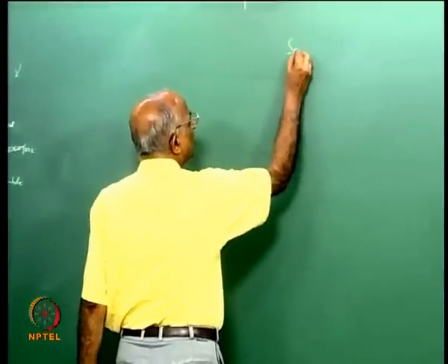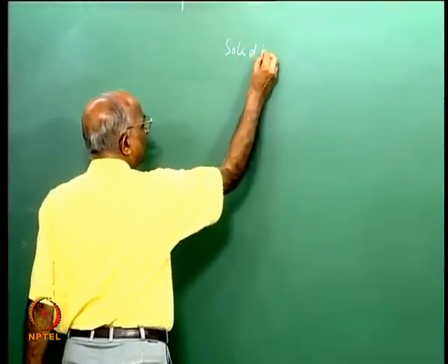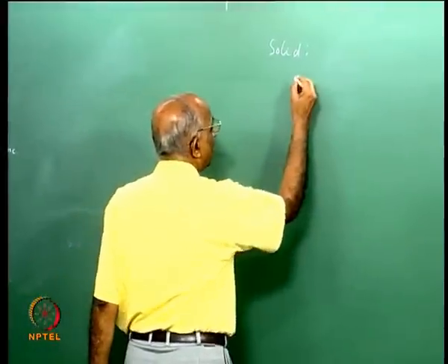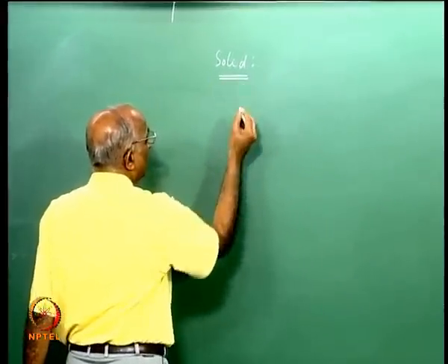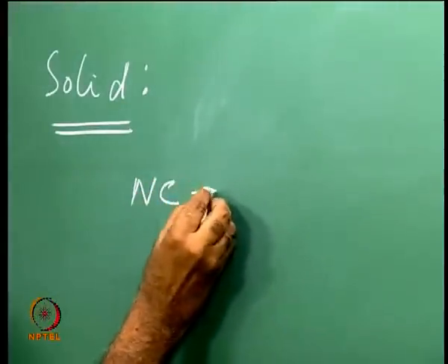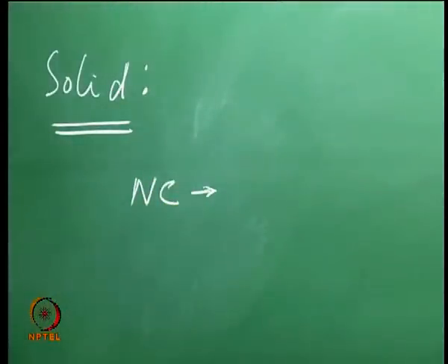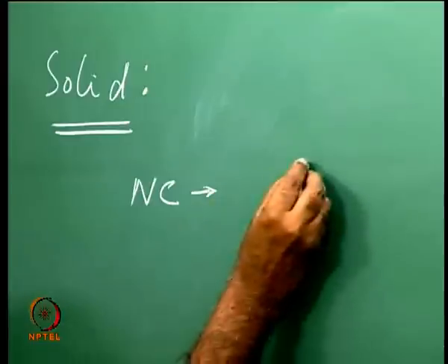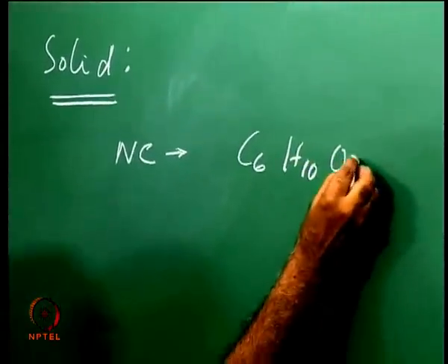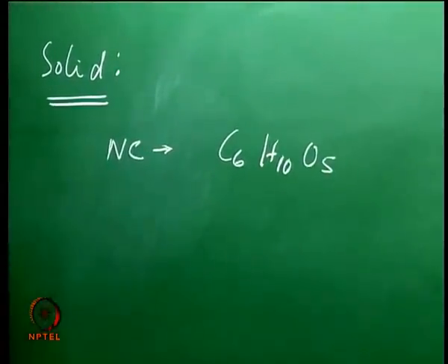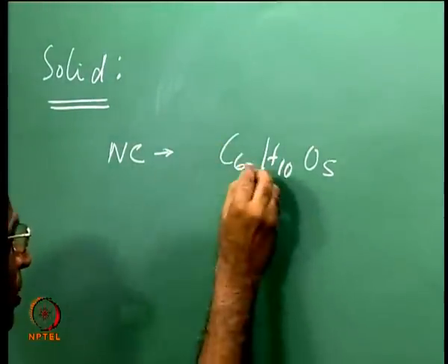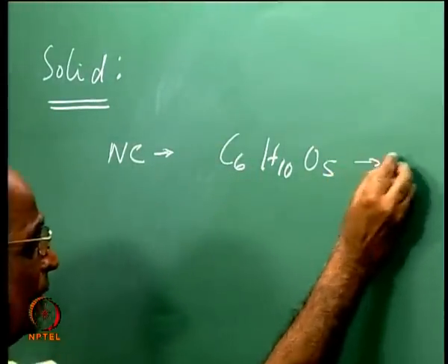Well, solid propellants, we have already seen the different chemicals. Let us start with the chemical with which we started in solids. We said I could use something like nitrocellulose, which we said is an explosive. And what was the formula for nitrocellulose? We had something like C6H10O5, was it, or is it O10H5? C6H10O5 was cellulose, and what I did to the cellulose is like paper.